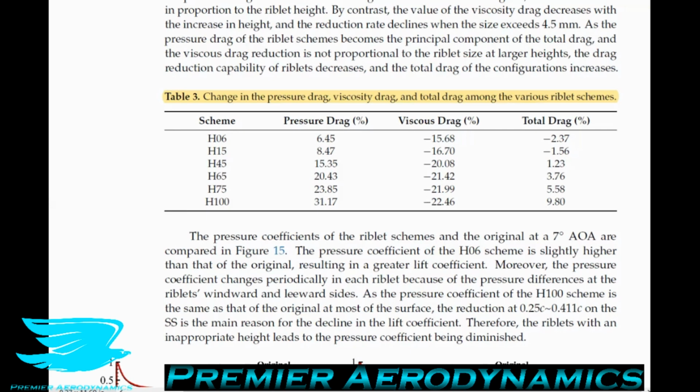So in other words, as we saw before with the riblets, in the troughs we have a lower wall shear stress, which means a lower local friction drag. At the peak, we get an increase in the friction drag, but they average out to be a reduction in the friction drag overall. Now, for these riblets, as long as they're not ridiculously big, they will get a reduction in the drag. As they get ridiculously big, then you don't get a reduction in the drag.